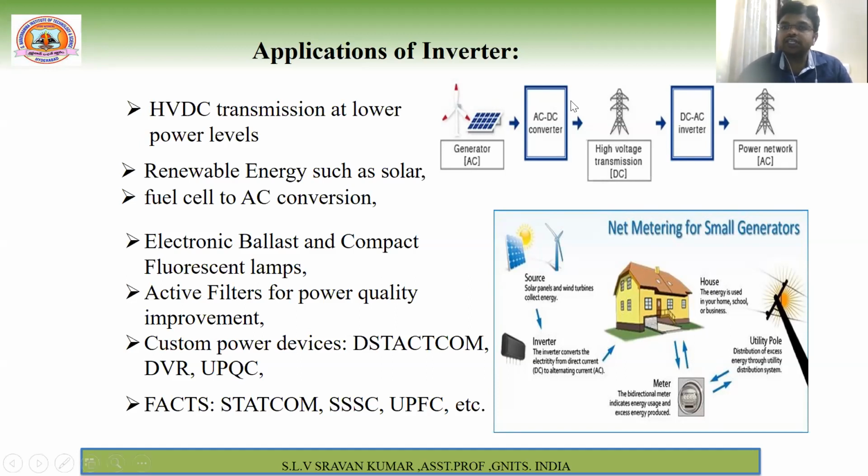So that is the advantage. Therefore, losses will be less, but some initial costs will increase because we are using an AC to DC converter, some protective equipment, all those things. But losses will be reduced, and again at the receiving end, we have to convert DC to AC only because 90% of the loads in our home appliances are AC.